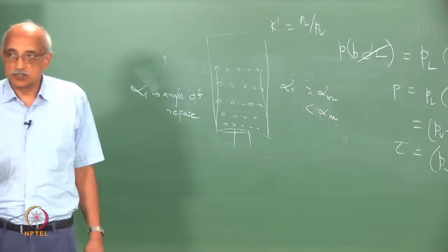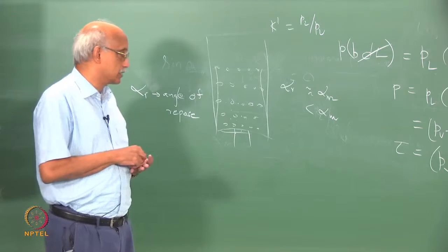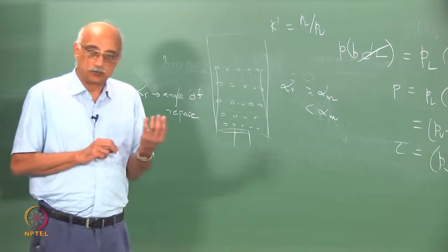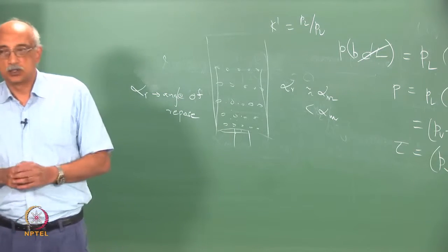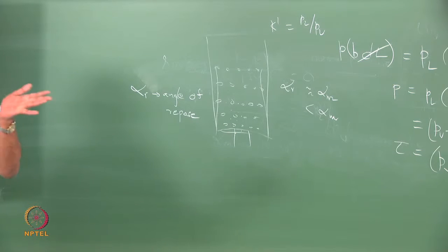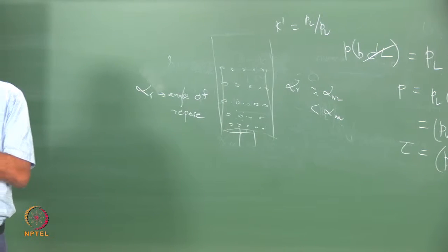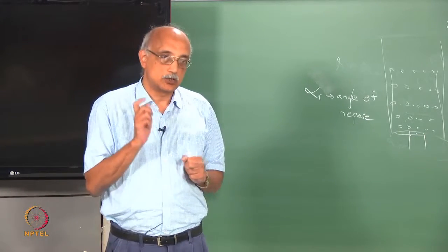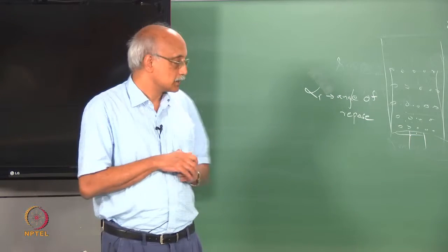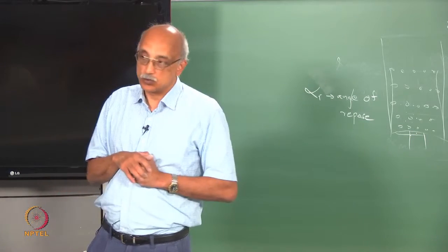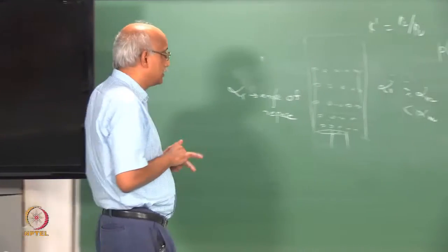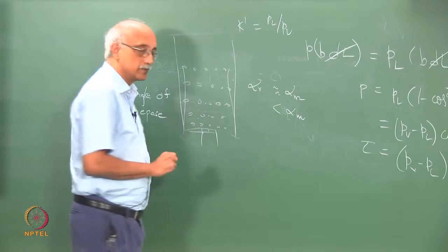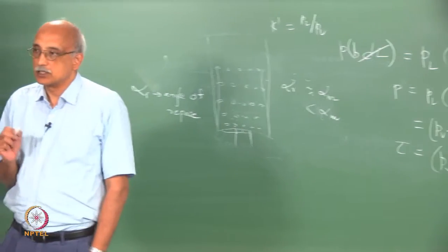So, that is the time sequence of how discharge happens, and if you look at what controls this behavior, the initial flow where the column starts to flow, as well as the conical or funnel flow when it slowly starts to expand into a cone, are controlled by the value of alpha m. Whereas, once the flow has been set in motion and you start having participation from the material along the walls or at the bottom, then the angle of repose has a significant influence.